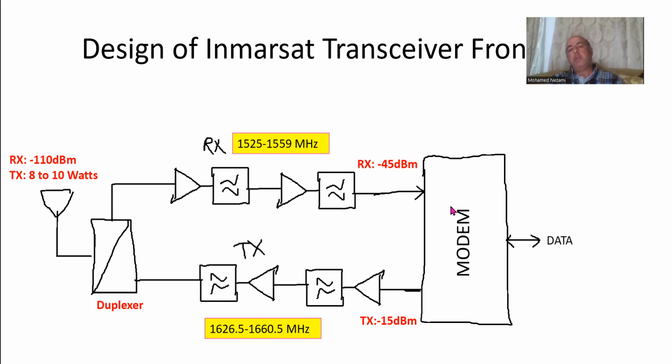But if you have a quadrature down converter and quadrature up converter, then you can introduce all the quadrature impairments and look at the effect of phase noise, and so forth. Of course, here we don't have any phase noise issues from this section, because, well, we do have a little bit from the PA, but that's negligible right now.